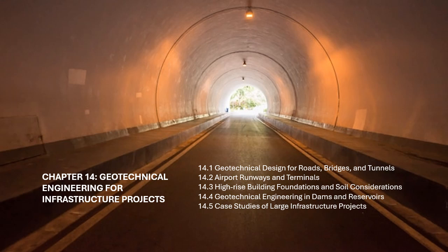Earthquake resilience and seismic design. In seismic regions, airport terminals must be designed to withstand ground shaking and minimize damage during an earthquake. Geotechnical engineers use seismic site response analysis to assess how the soil behaves under dynamic loading. Foundation systems may incorporate seismic isolation technologies or deep foundations to enhance the structure's resilience to earthquake-induced forces.